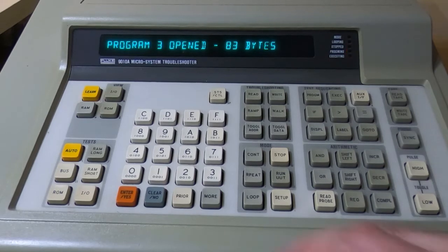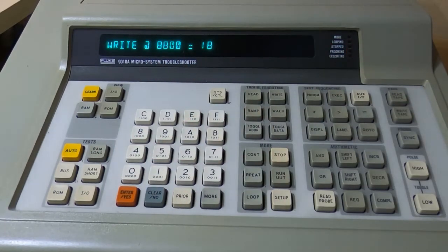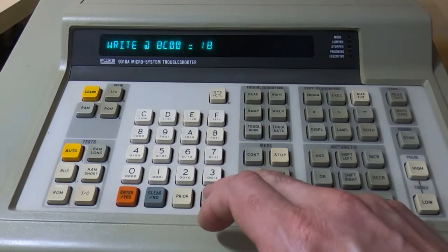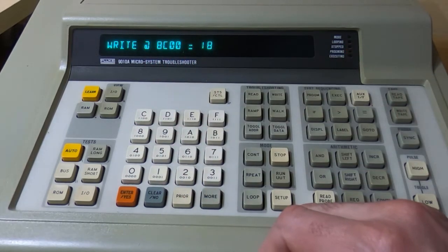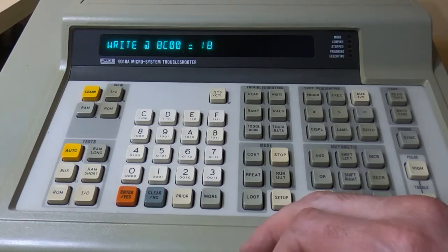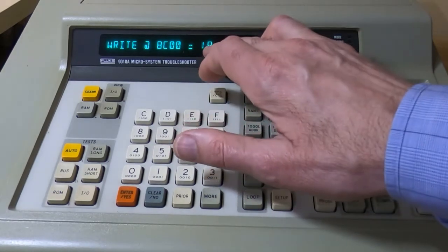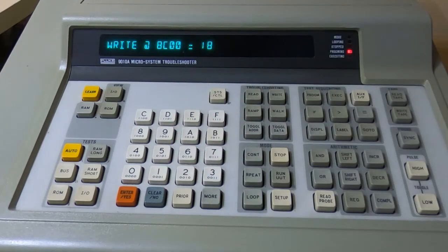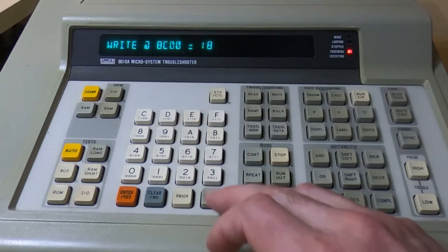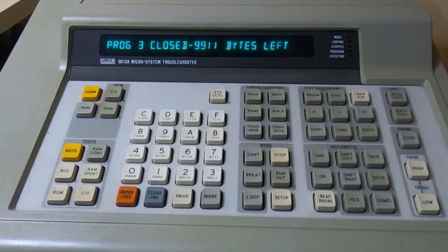Okay, so I've created a third program, and if we have a quick look through, it's very simple. All I'm doing is writing the binary values that we determined we needed to write the uppercase A, and I'm doing those on subsequent horizontal lines. Now of course, because we're using an interlaced display, they're not consecutive lines, so it's a very quick bit of maths, and it was easy to determine that each line is 400 hex bytes stepped on from the previous one. So all I've done is assume that each row of the character is 400 hex bytes displaced from the previous one. And so as we go through, you'll see that the address we're writing to jumps up in values of 400 hex, but we're actually writing the next byte value on the next actual scan line on the display, not 400 hex lines down. So that's all it does. It just goes through and writes the values we need to write the uppercase A. So I'll move the camera, we'll have a look at the display and see what that gives us.